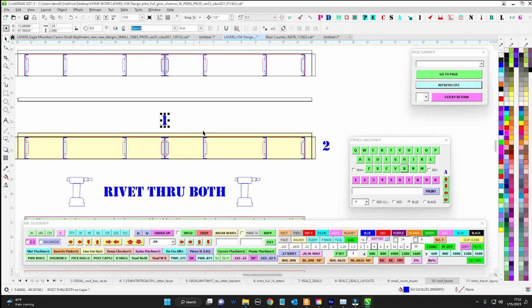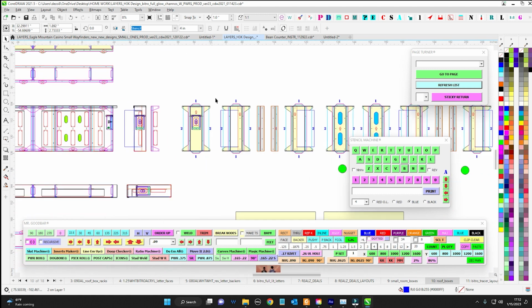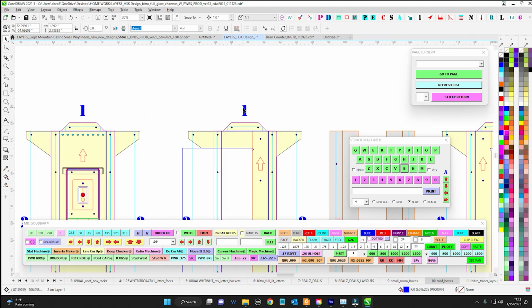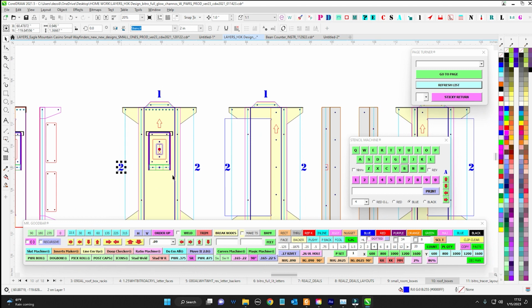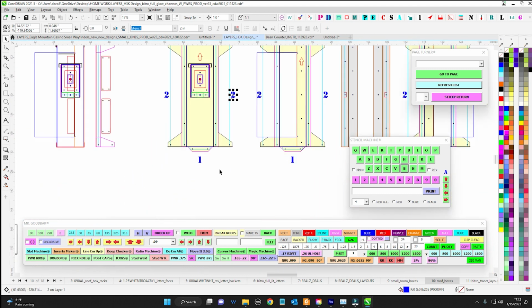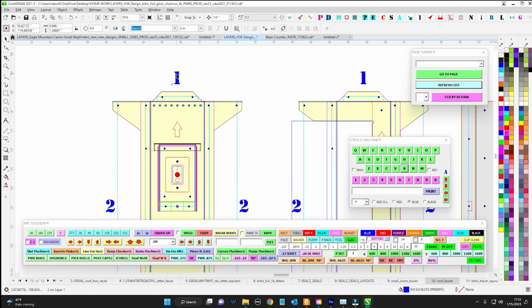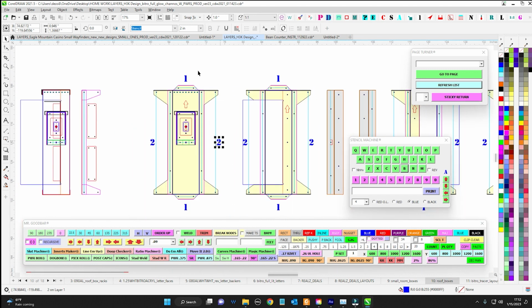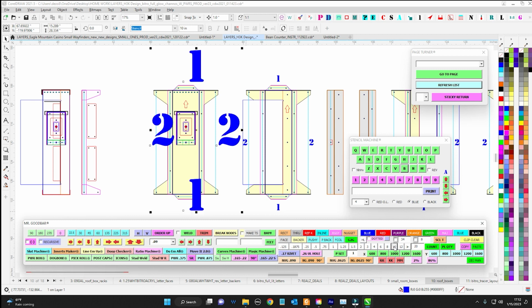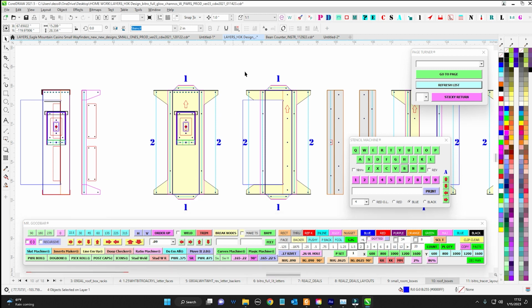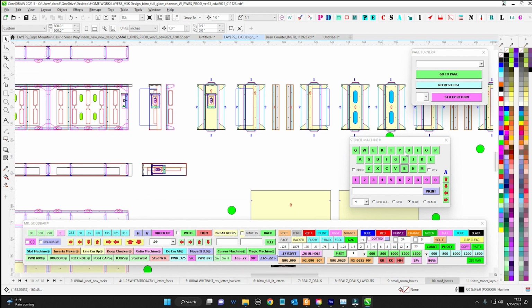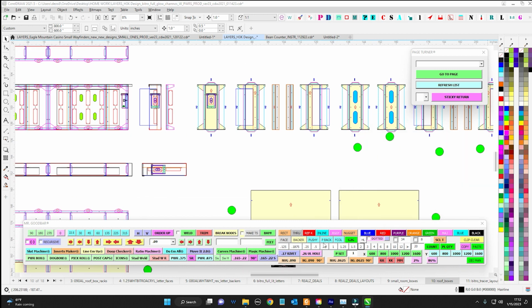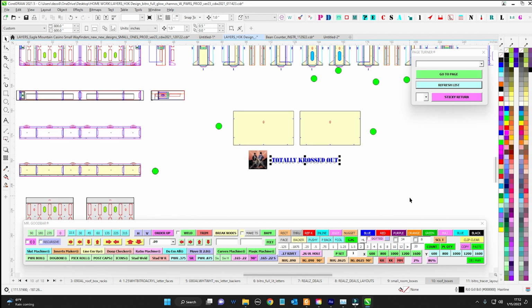There you go. A lot of times these numbers here denote the bend order. So I'll have these letters on the sides and on the top and the bottom. And sometimes these come out a little too big, or a little too small. So these are 2-inch right now. All I need to do is select them, and I can make them an inch, 1.5 inches, 2 inches, whatever looks good. Obviously 10 inches is way too big. So this allows me to quickly change these things as fast as possible by having dedicated hot buttons that do all that work for me.